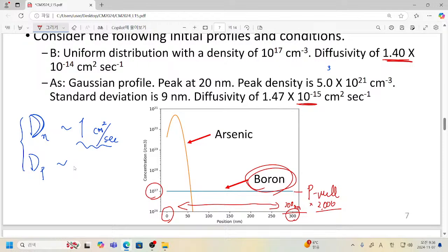So boron density extends over quite a long range, around a few micrometer scale. For the first few micrometers, we can still treat this boron density as a constant, and eventually it will roll off and go to zero. However, since our simulation domain is restricted to the first 300 nanometer, it is completely okay to say it in this way. Okay?